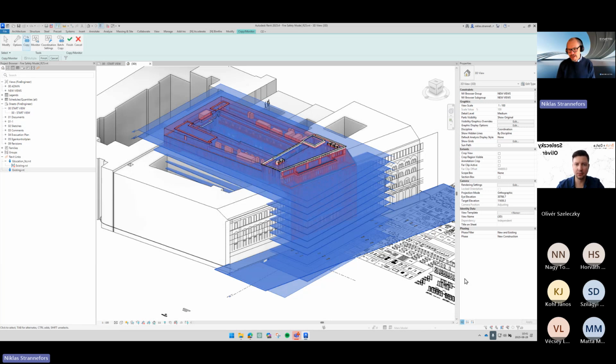So now in the bottom right-hand side, we don't have 4,304. We have 23. And here, a lot of people don't press the green finish. You press the small finish next to multiple. Otherwise, it will not copy. You just finish the command without copying anything. As I mentioned, worst user interface ever designed.